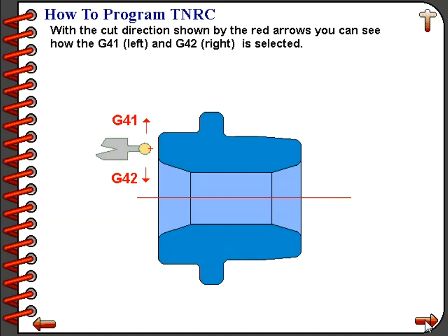Looking in the direction of cut, the tool would be on the right of that path, meaning that we should command G42.